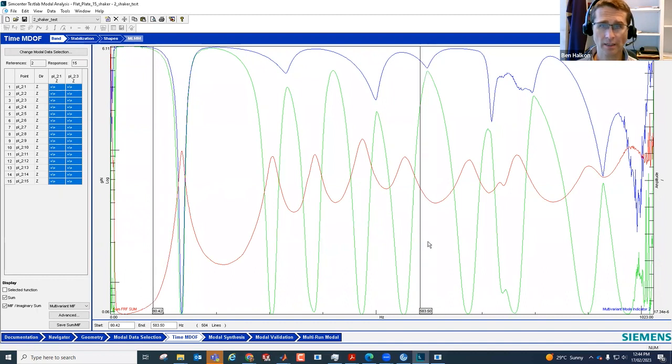We typically start at a trough in the sum FRF. The red curve is the sum FRF. So we're going to have a look in this frequency range from 80 Hertz to 611 Hertz. You can see there's a trough here. There are a number of resonant frequencies. The mode indicator function drops twice here, suggesting 2 frequencies close together, and 1 frequency at each of these subsequent peaks. And then we move along the mini workbook here to the stabilization diagram.